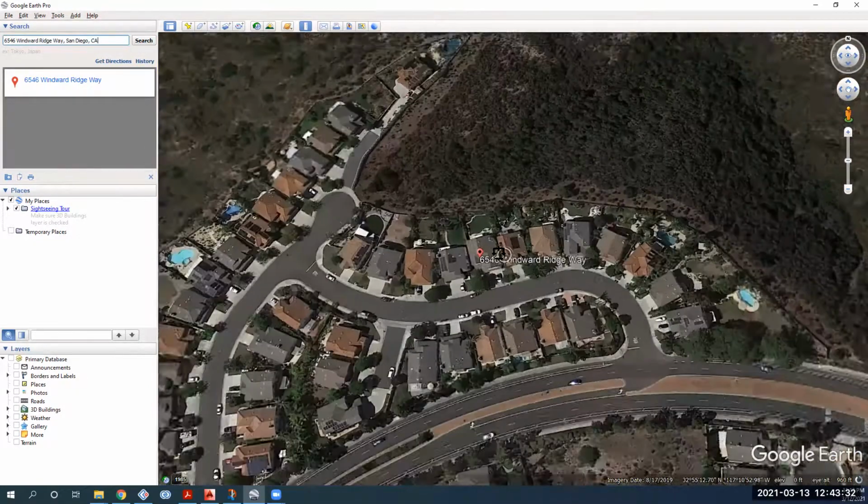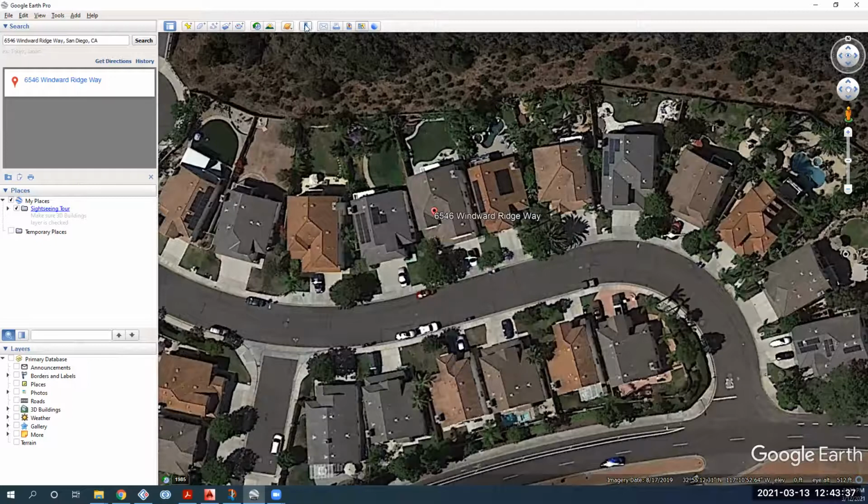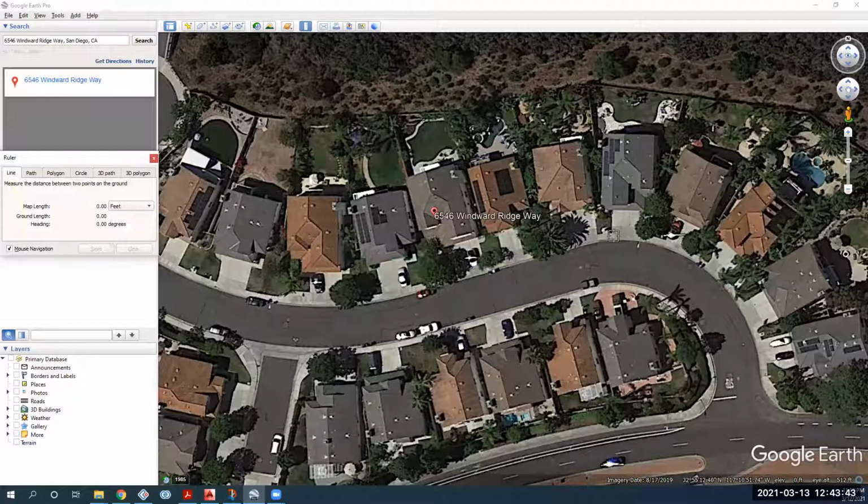Although this is not the same year, I'll open up the scale again. So you go to scale, and then the scale thing pops up. Press R so that again it's oriented in the north-south direction. And then you pay attention to this: you see this length, and you see these degrees. So you turn on mouse navigation, and you try to stretch this line and keep the degrees at exactly 90. Yeah, that's it. Then you take a screen grab.